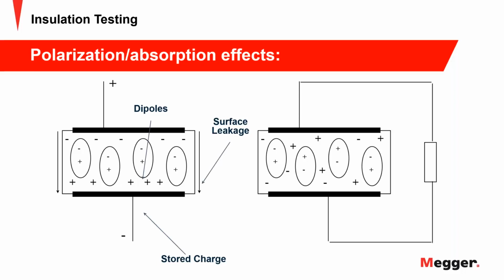As these large molecules adapt themselves and orient towards the charge, then charge is moving, and current is a movement of charge. That is your charging current. And over the billions of molecules in a large piece of equipment, that adds up and becomes significant. So next.